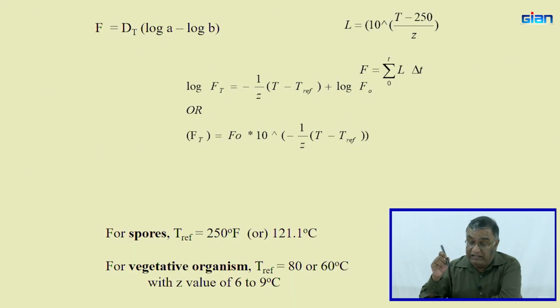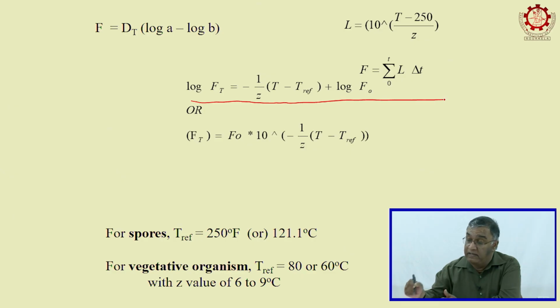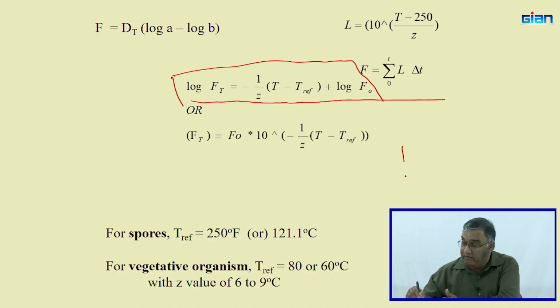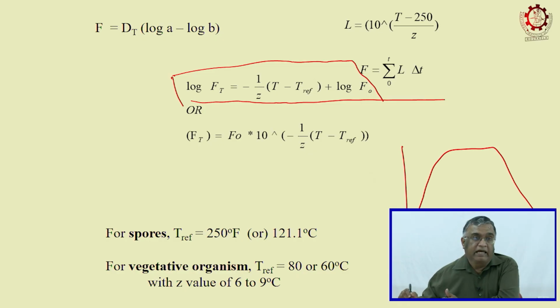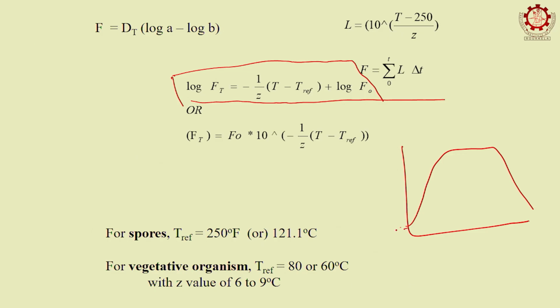So the next equation we are going to use is this relationship here. Log Ft is going to be this here. So basically, when I have canning equipment, initially maybe at 25 degrees Celsius, and then it's going to go to 121 Celsius, and then you are going to process say 30 minutes, and this come up time maybe, I'm just making up some numbers, 15 minutes.